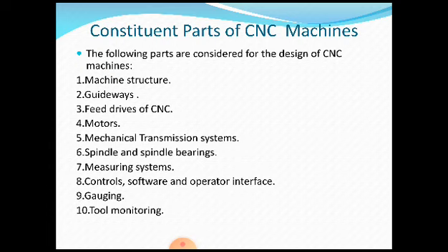The next one is guideways. Guideways, as the name itself implies, are the ways which are perfectly designed for the movement of your tools, turret heads, or even the tailstock, where the movement has to take place properly whenever the machining operation is being carried out. All these components we are discussing in detail in the subsequent presentations.